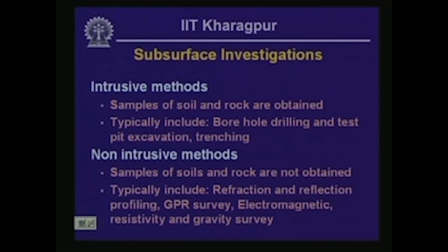Then non-intrusive methods also include GPR survey, in which ground penetrating radars are used, or as in the previous procedure of reconnaissance, detailed electromagnetic, resistivity or gravity survey can be undertaken in the non-intrusive method in greater detail.